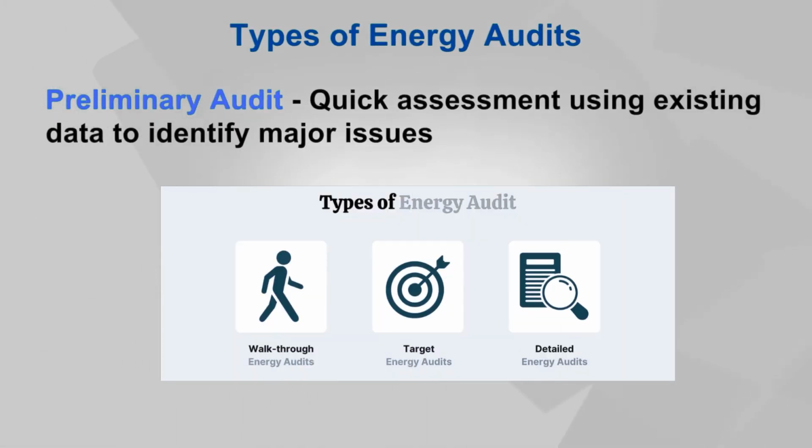A preliminary energy audit, also known as a simple audit or walkthrough audit, is a basic assessment of energy usage. It involves a quick evaluation using existing data and is designed to identify immediate improvements and set baselines for further analysis. This audit relies on readily available data such as energy bills and basic facility information to estimate the energy consumption and identify obvious areas of inefficiency.